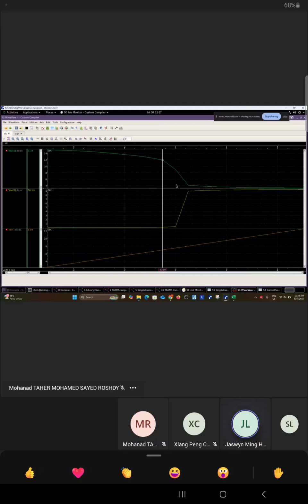No, I cannot say it's a pole, right? Because you are plotting against Vin. I think not a pole actually. Somewhat like when you increase the Vin into this region, I think one of your MOSFETs starts behaving already. Yeah, I think actually the working region is here. The working region is 0 to 0.4. Actually it declines, right, when you increase V supply. As for the I tail, tail current.